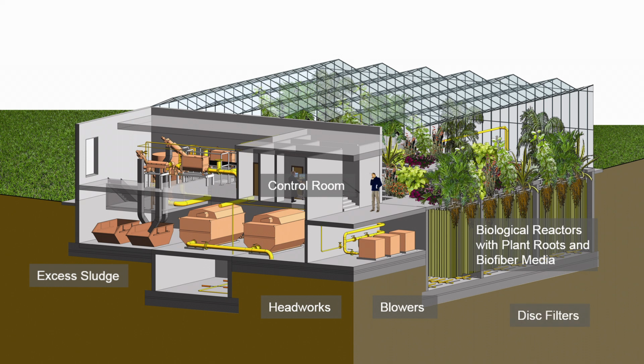In the Organica plants, as you will see later, it is possible to forego the clarifier, the traditional large clarifiers, and directly go from the biological reactors to a microfiltration unit. This way, it is possible to save all that space and really create a very compact structure.